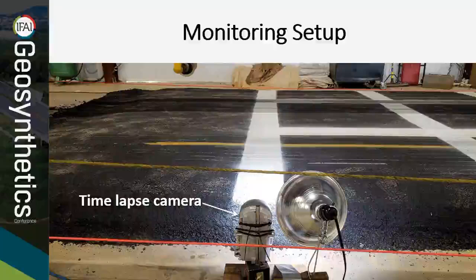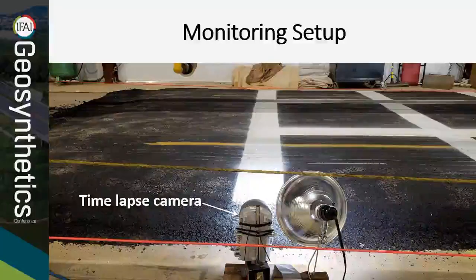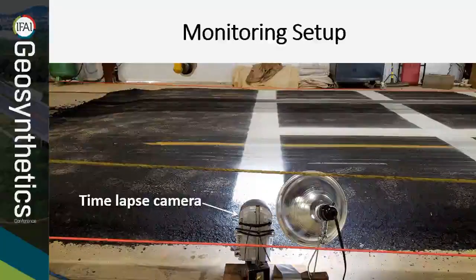Knowing the traffic level as a function of time was to help link traffic level to the appearance of the reflective crack. The idea was that the test sections with cracks appearing at lower traffic levels performed worse than test sections where the crack takes longer to appear. Using this data, benefit could be calculated as the ratio of traffic passes of the reinforced test sections as compared to the unreinforced or control test section.